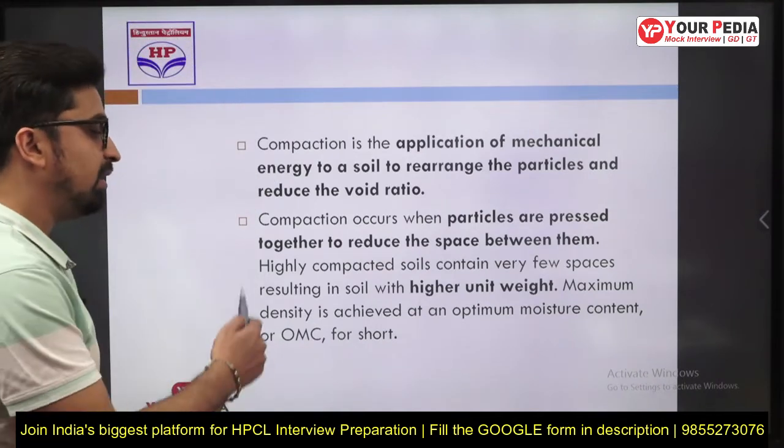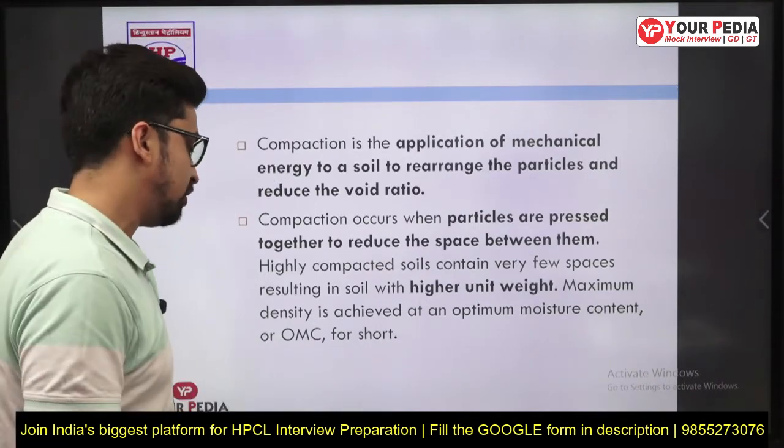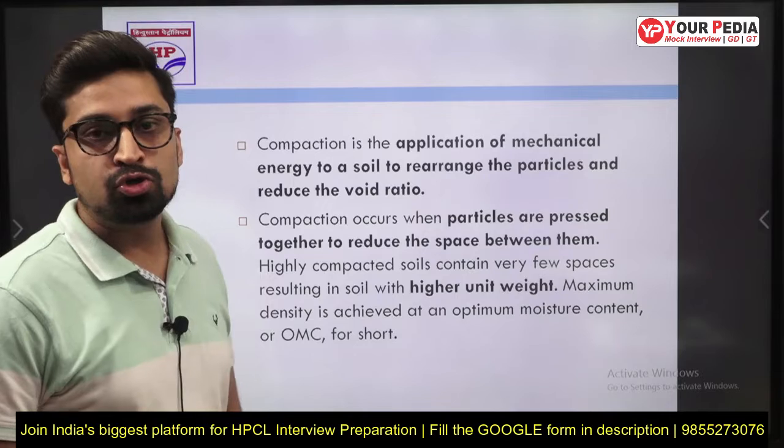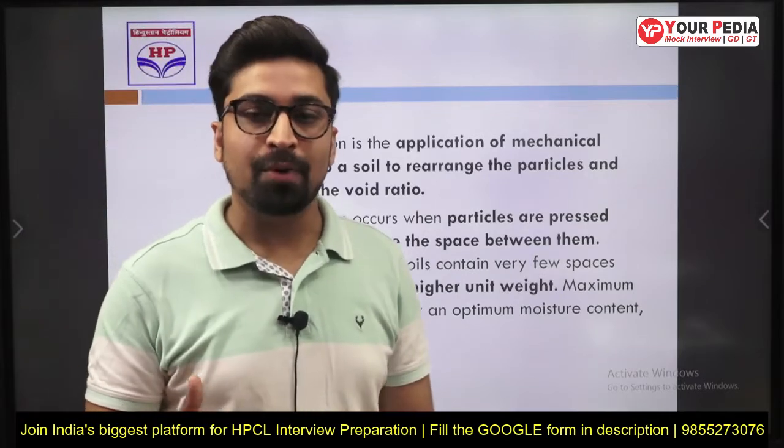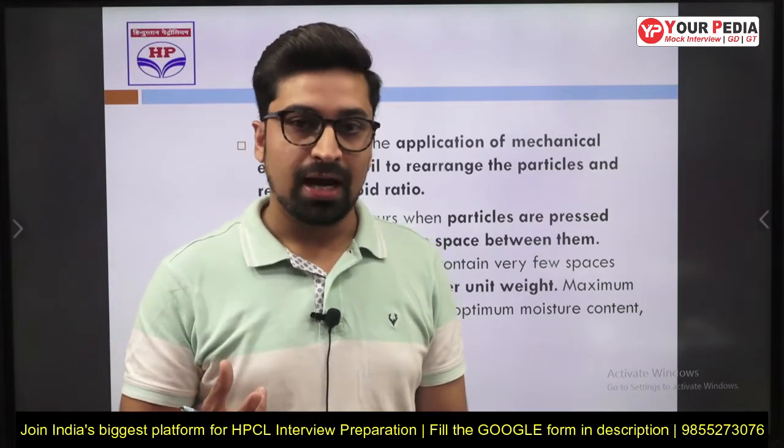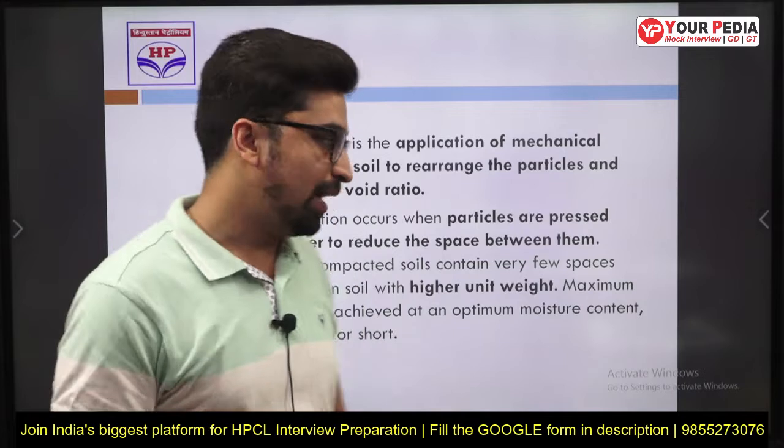Also, the maximum density is achieved at an optimum moisture content, or OMC for short. So there's an optimum moisture content, or water content, at which you get the maximum dry density.